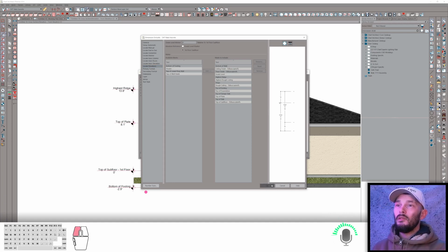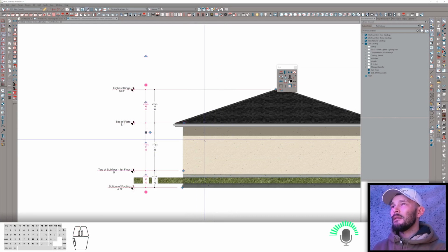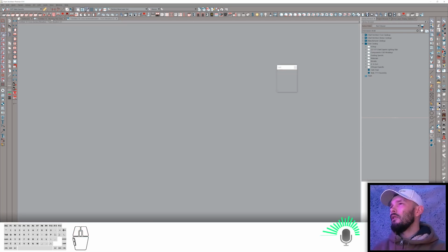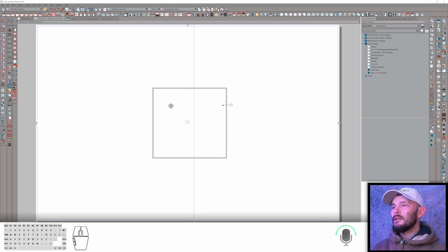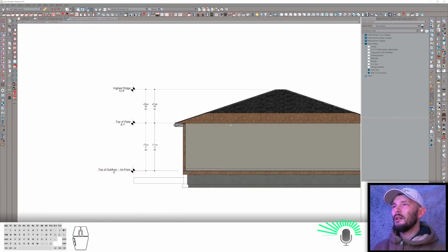And you can always go in here and snap new elevations, right? So whatever elevations we can pick up, if I grab this continuation diamond here and I snap it to something that's relevant, it's going to pick up some additional markers, right? Now, sometimes this is a little bit difficult to pick up any kind of snaps. And something that I encourage people to do if you're trying to locate something very specific is go into your camera, drag it through so you create a cross-section cut. And with that cross-section cut, when this updates, you might be able to grab some additional elements.